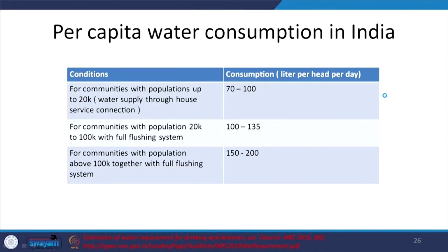So we now know until what period, and from that we know what population to cater to. Now that I know the population, I need to know per person, per day, what the water requirements are. So depending upon where they are, it varies depending upon the kind of water usage, but typically if it's in cities, you know more or less the functions that water is used for, and you can come up with an average value, right? So per capita water demand in India is around 135 liters per person per day, right?